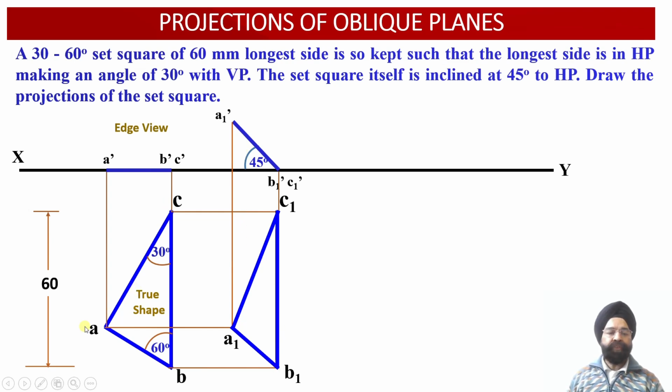And from the 3 points of the previous view, that is in the plan A, B and C, we have drawn 3 horizontal lines over there. And wherever these 3 horizontal projector lines intersect with the corresponding projector lines appearing downwards from these 3 elevation projection points, we'll be able to find points A1, B1 and C1.